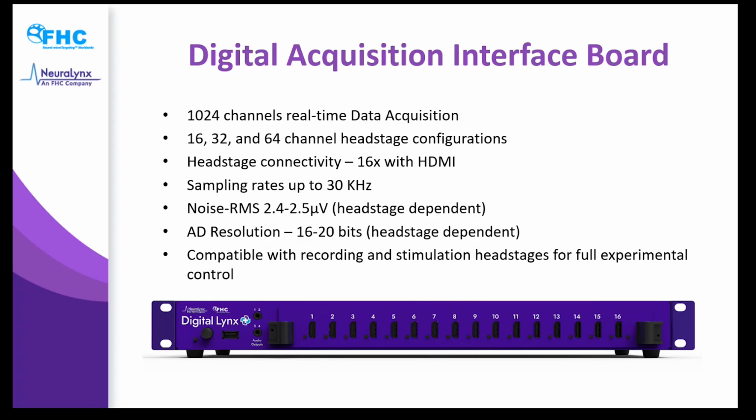Noise is between 2.4 and 2.5 microvolts depending on the head stage, and then the A/D resolution is 16 to 20 bits, head stage dependent. Intan based head stages, which are ones we currently have, are 16, and then the new iLinks will be 20 bits. And this will be compatible with recording and stimulation head stages, full experimental control. So the iLinks head stage that will be coming out will be our version of the STEM head stage, and then Intan has a 16 channel 2116 that it will be compatible with.